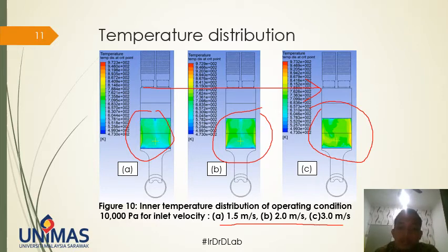The solidified molten metal might trap the air bubbles, thus leaving insufficient molten metal to completely fill the section. The different cooling rate can cause shrinkage to the cast product and increase porosity defect due to non-uniform solidification.